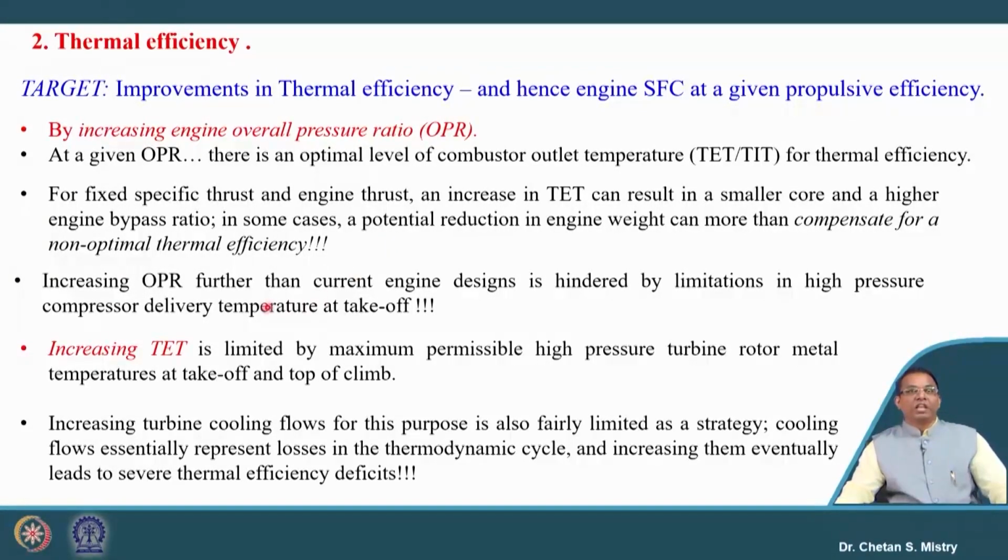So, if we improve the overall pressure ratio further than the current engine, then it will put a limitation in terms of the high pressure compressor delivery temperature at the takeoff condition.